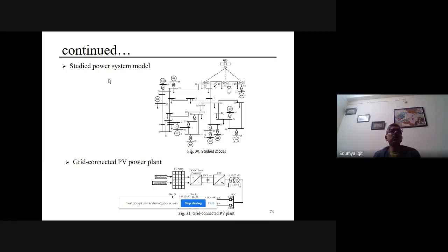So for your zone 3 operation in the presence of harmonics, the extraction of the fundamental phasor is very straightforward. You go for a half cycle data window, DFT, or a full cycle, and correspondingly you get the fundamental phasor with the minimum spectral leakage.